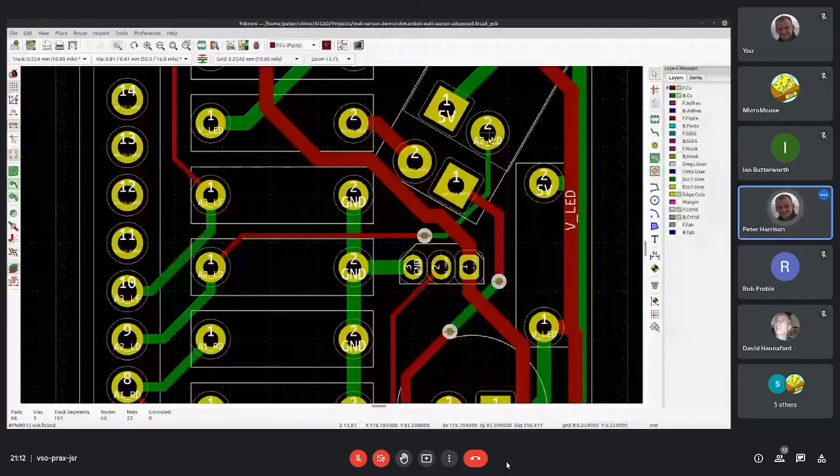A trace on the others, and I thought I would just be happier with a thicker trace. So let's do that. We're on the top copper layer. We'll select the trace tool, and we'll start. What I didn't do, of course, was change the size. Come up here and select 0.5 millimeter, and I'm just going to come up and you'll notice that it gets rid of the old trace for me.